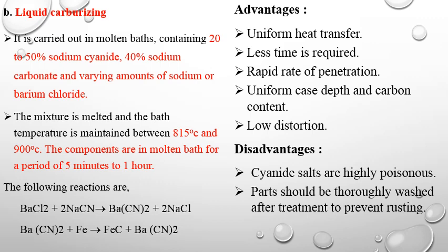Again, the advantages are uniform heat transfer, less time required, and low dissociation. The disadvantage is that the cyanide salts are highly poisonous. The parts should be thoroughly washed after treatment to prevent rusting.